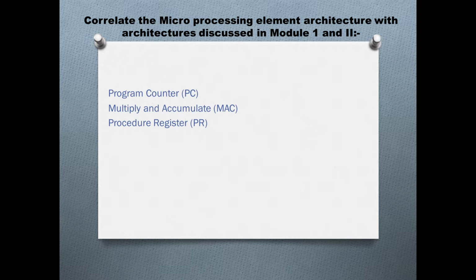Right now there are two versions of CPU existing inside the MSP430 microcontroller family. The program counter includes a 20-bit program counter that points to the next instruction to be executed. Each instruction uses an even number of bytes, 2, 4, 6 or 8 bytes, and the program counter is incremented accordingly.